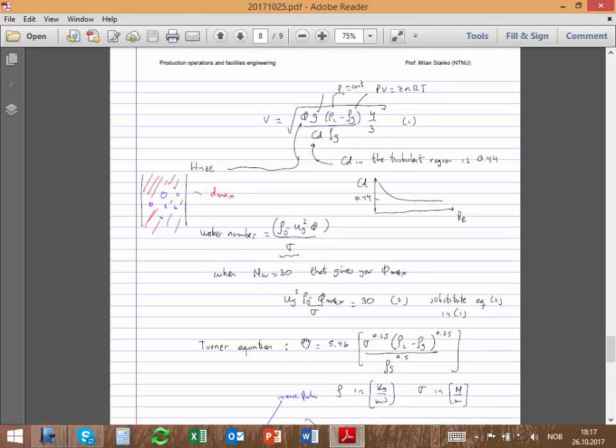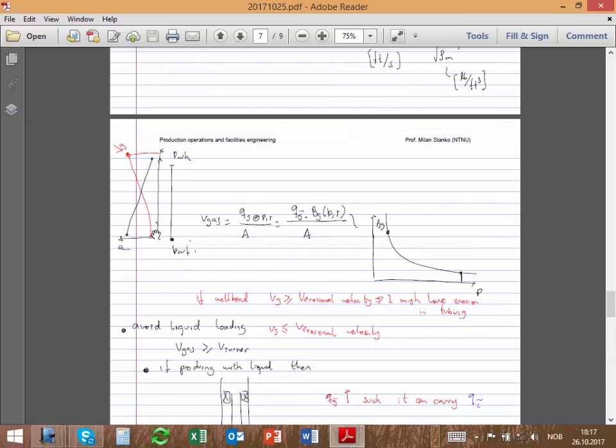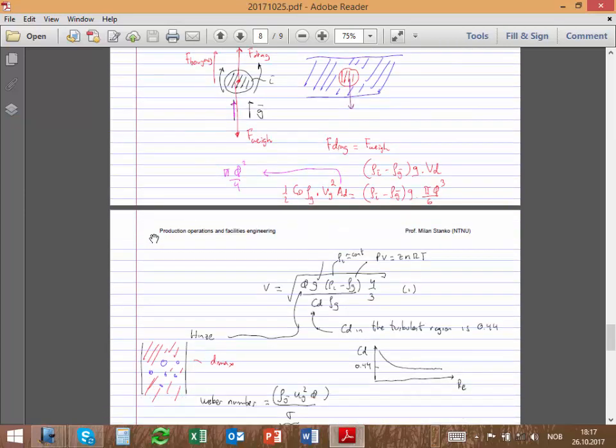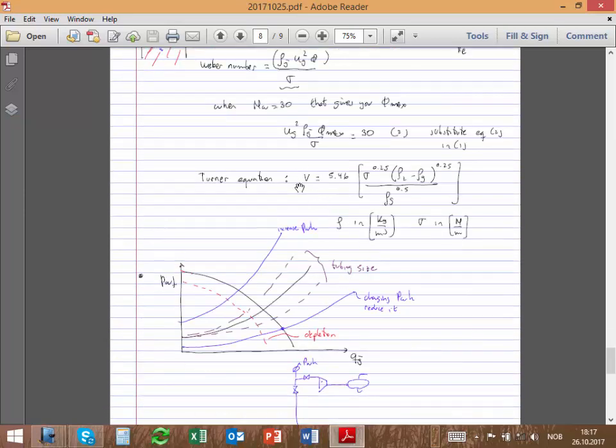Okay, so for exactly the same, the velocity will be smallest usually at the bottom hole. Okay, exactly coming out of the formation. That will be because that has the highest pressure, the smallest volume, and then the smallest velocity, right? And because it is the smallest, that's the most critical point for liquid loading usually.